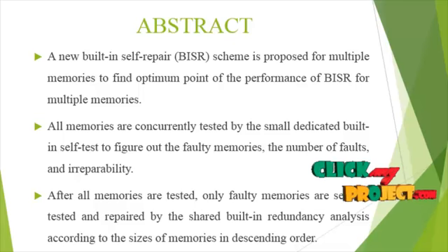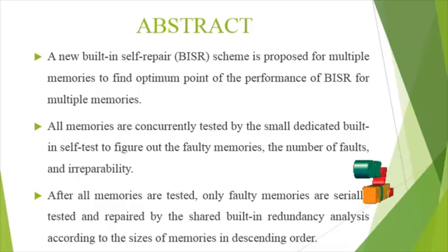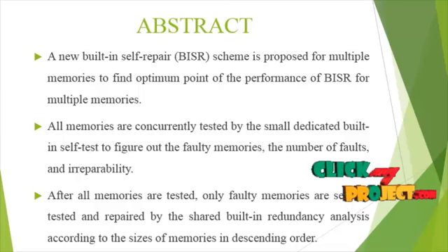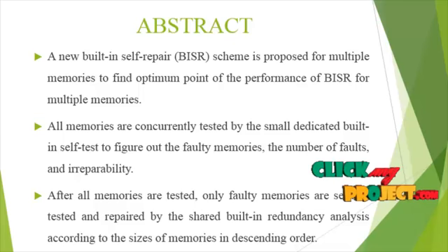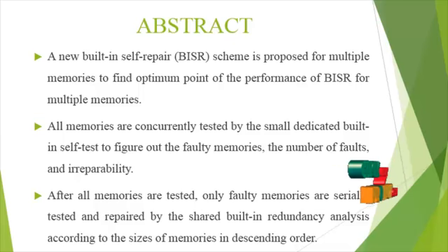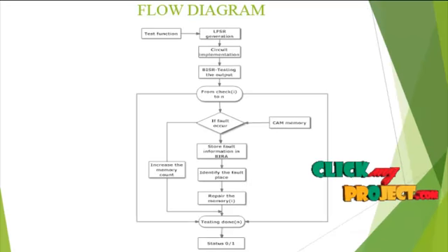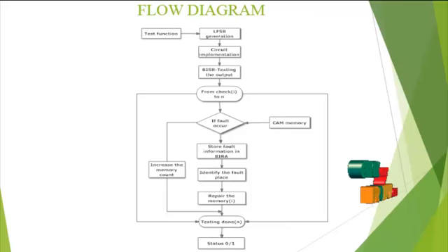The memory BISR as a concept contains an interface between the memory BIST logic and the redundancy wrapper for storing faulty addresses. There are various BISR schemes for multiple memories because routing, timing and power consumption are realistically considered. Next we are going to see the flow diagram for our product.